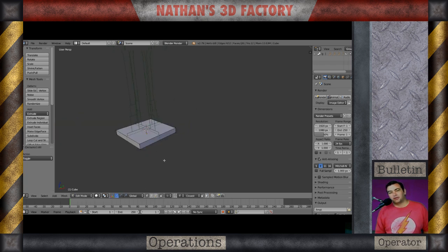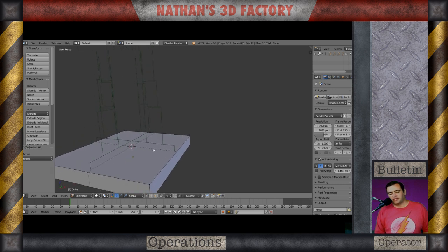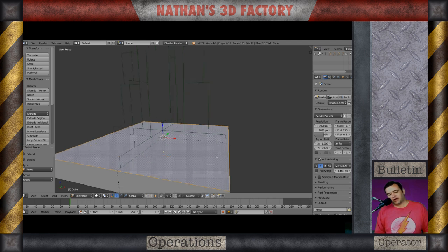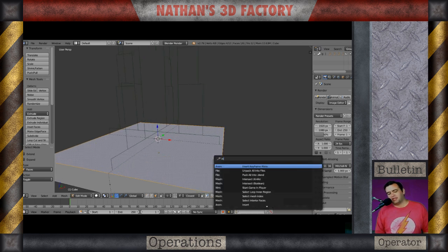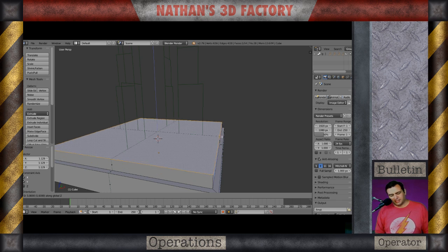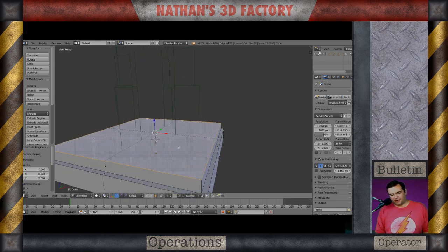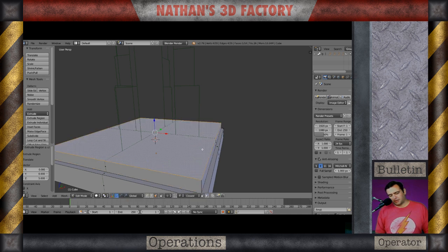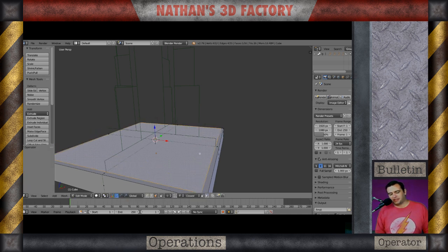So I made sure to go to vertex snap mode for that. And as I'm doing these, I'm only doing these along certain axes. So I'll either isolate those so that I'm not including the Z-axis when I'm scaling, or I will do just the Z-axis or the Y-axis depending on where I'm going. So in essence what I'm doing is kind of like a 2.5D snap. Alright, so what I'm doing now is I'm insetting some faces and extruding upward.